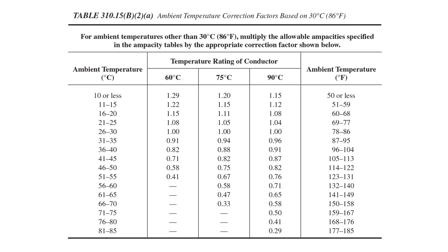The temperature itself already brought that insulation up to its maximum value, and you couldn't put any additional current through there. And it's also possible, especially if you're in cold places like the Arctic or Antarctic, where cold temperatures dissipate heat better than the warm temperature. So the temperature differential has a big impact on how much your conductor can dissipate the heat. So you can actually go up in ampacity if you were, say, operating at 18 degrees instead of at 30.